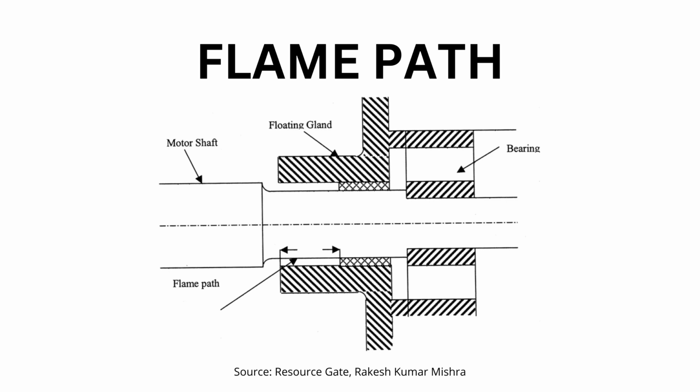Explosion-proof motors are designed with thick, hardened cases to contain the pressure of an initial explosion, and they must allow hot gases to escape in a controlled way that does not create an ignition source. To do this, they use flame paths, which are long, narrow corridors through which burning gases can escape while being cooled to a safe temperature. Flame paths are usually built into the shaft or body of the motor.